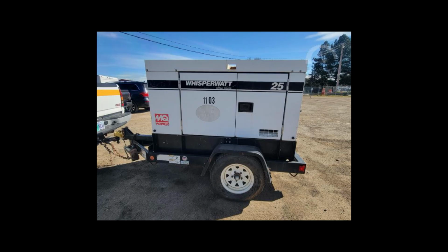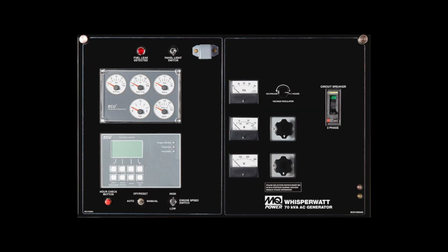Some large generators or tow plants have an option to increase the voltage straight from the source. This is very handy and can generally allow up to a 5% increase in voltage, but any more than that, you could risk destabilizing the generator and its components. So we could send 126 volts from this genny and end up with 120 at the end of the line, depending on the length and the amperage pull. Pretty cool feature, but again, usually it's only on tow plants or more expensive generators.